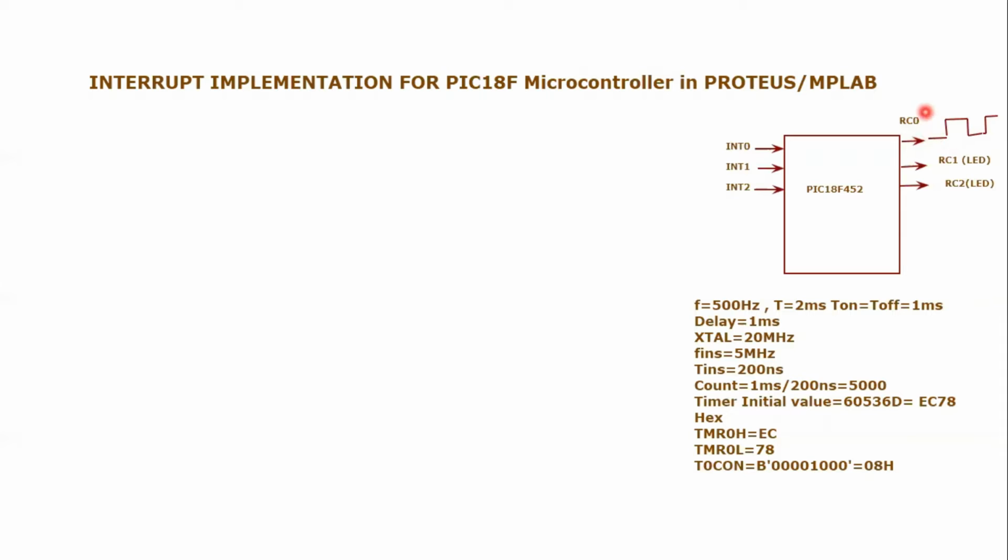Progressively. So what we do, we will use a timer here, and in this example we will be using the timer as an interrupt, right? So there will be an interrupt whenever the timer expires. The microcontroller will go and toggle this LED and then come back to the main code, and again when the timer expires, the microcontroller will go back to this LED and toggle it, and so on, right?